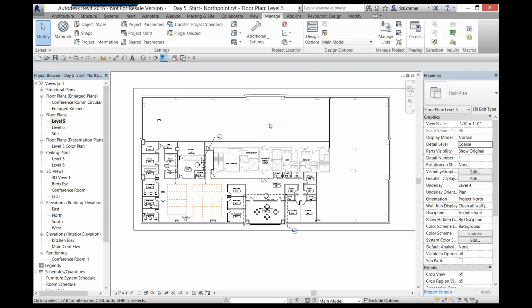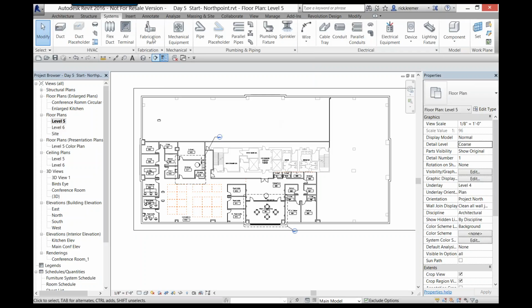Yes and no. I know it exists. Quite frankly, I have not used it. One of the things that you can do within the Revit MEP environment, and that is the systems environment here on the screen, after you place the systems, you have the ability within Revit to click all these different area rooms and spaces, and they will calculate the quantity of air required.